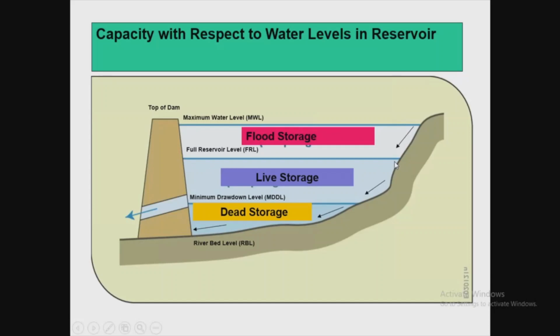1950 means now it is 70 years. So after 70 years, the dam might have filled with sediment, it might have encroached on the capacity by around 50%, we can say, and if it is in a hilly region, it may be more also. So it is necessary to survey all the reservoirs available in Madhya Pradesh or elsewhere to assess the capacity.